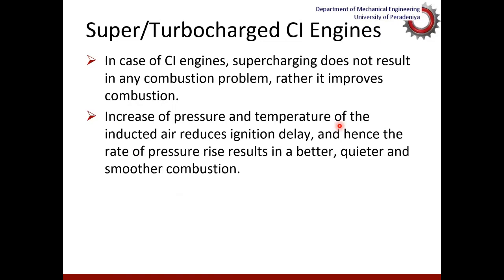Turbocharging was initially used in compression ignition engines traditionally, and in compression ignition engines, there is no issue with auto ignition. Anyway, it is an auto ignition process. Therefore, you can have higher temperatures at the beginning of the compression as well as combustion. So that would improve the combustion process, reduce the ignition delay, reduce the combustion duration, and improve the efficiency of the combustion process. Therefore, turbocharging or supercharging is quite popular among compression ignition engines.